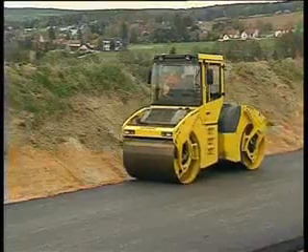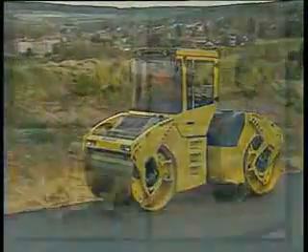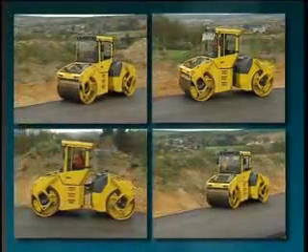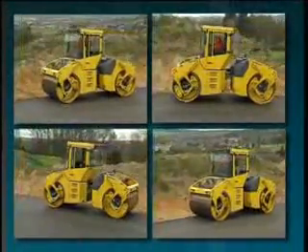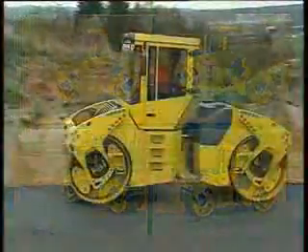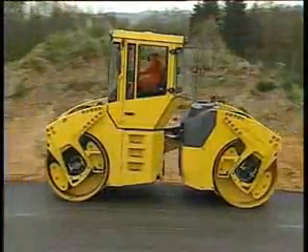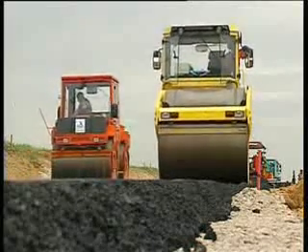However, problems frequently occur using compaction with a fixed amplitude. Too many passes, especially on pre-cooled mix, lead to over-compaction or aggregate crushing. A non-adjustable amplitude frequently causes the drums to bounce, which puts high stress on the entire roller, the driver, and on the surrounding environment.